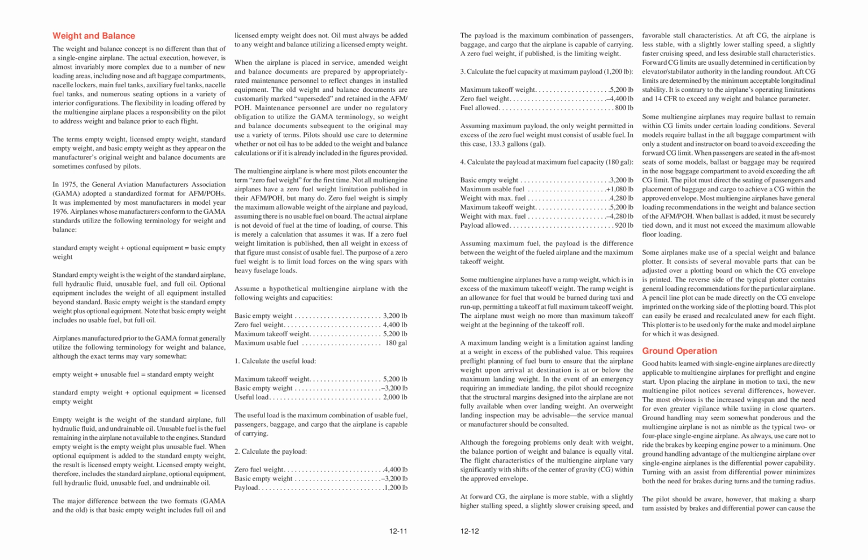One ground handling advantage of the multi-engine airplane over single-engine airplanes is the differential power capability. Turning with an assist from differential power minimizes both the need for brakes during turns and the turning radius.